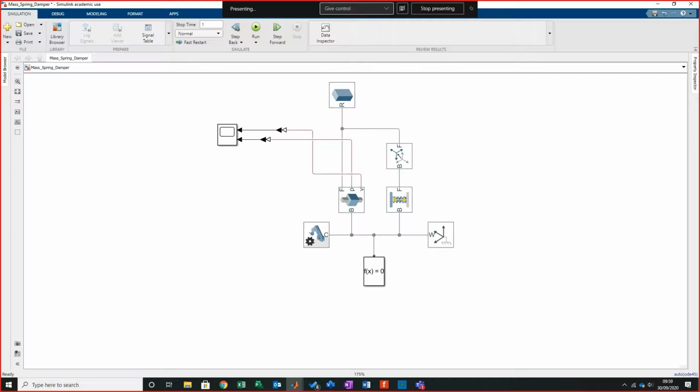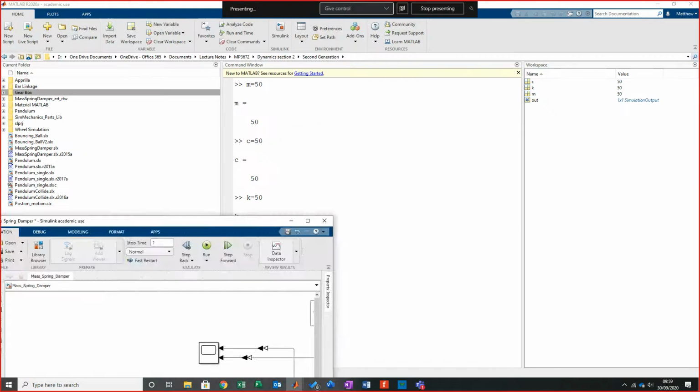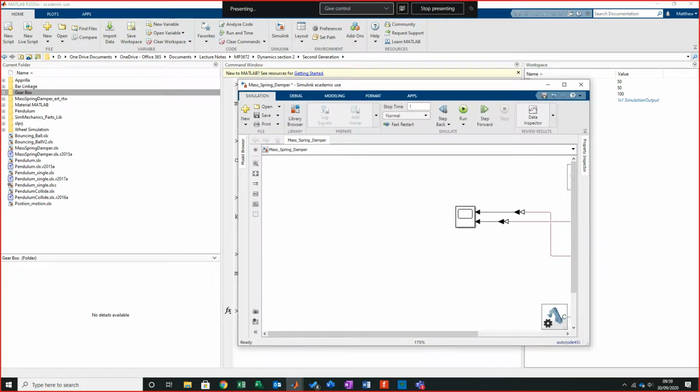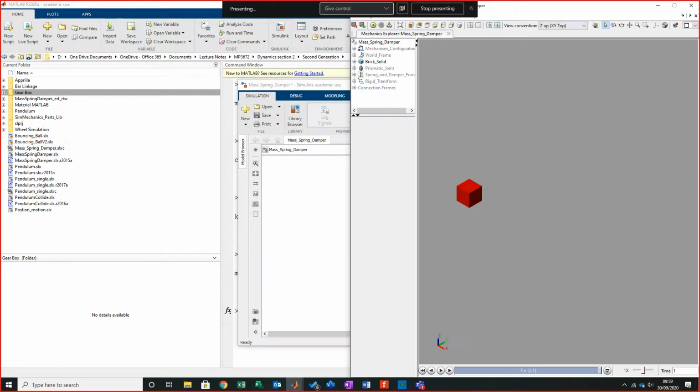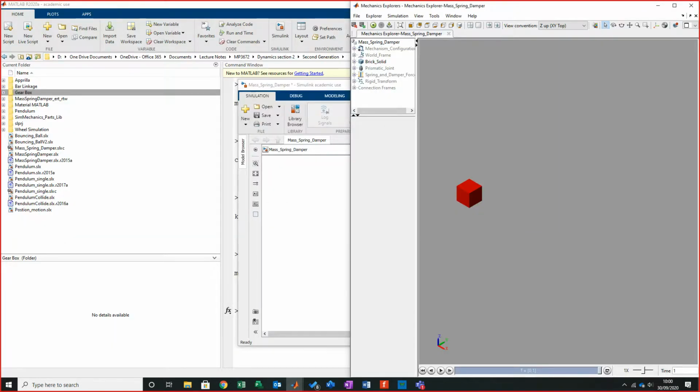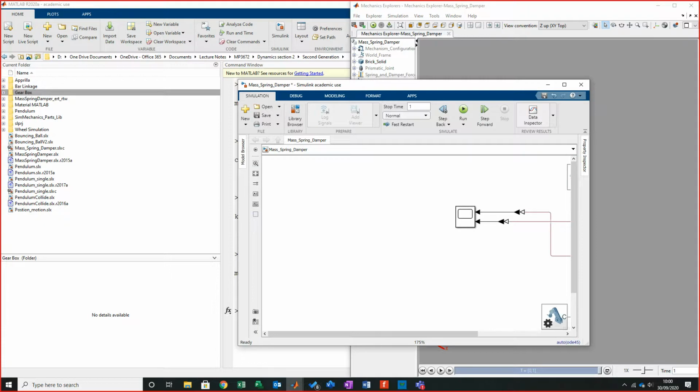However, if you're doing a gearbox, a variable piston, or variable conrod or crank ratios, it can be a nightmare changing everything over one by one. Often the best way of doing it is controlling these through variables. So if I run this, I've now got even more control by simply typing in M is equal to 100. Because that variable's changed, when I run it, it might go a bit wrong here because I've just randomly chosen a value. Now the mass is a lot bigger, and when it runs, we're now back in this state again. And don't forget, I set it by the density, so the bigger it gets, a greater density is going to emerge.